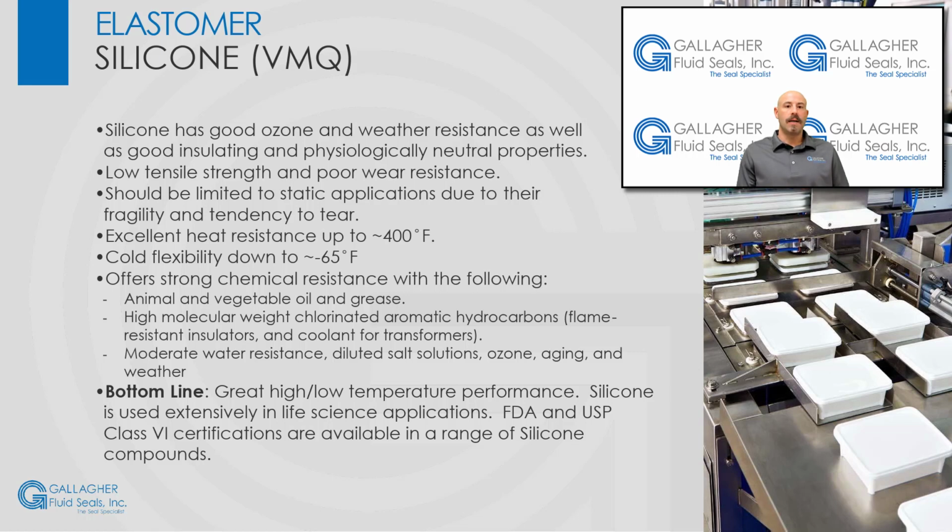The bottom line is that silicone has very strong high and low temperature performance. Silicone is used extensively in life science applications. FDA and USP Class 6 certifications are available in a range of silicone compounds. Silicone offers poor mechanical properties and should not be considered for dynamic applications.